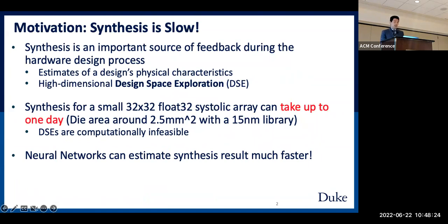Logic synthesis is an important step in the hardware design process. This step takes the user's input hardware description language and produces a cell netlist as well as an estimate for the power, timing, and area of the input design. Having this estimate can help in several ways. They can direct the developer towards the area of the design that requires more optimization, and by performing synthesis for a range of differently parameterized designs, this estimate can be used to choose the most optimal point in a design space exploration. However, synthesis is slow even for small designs.